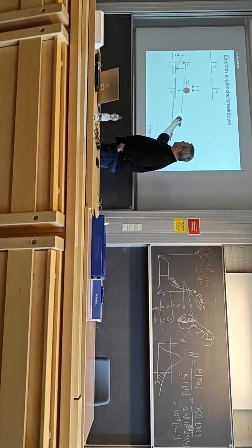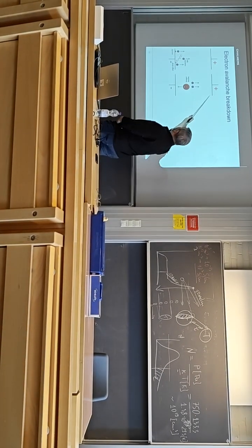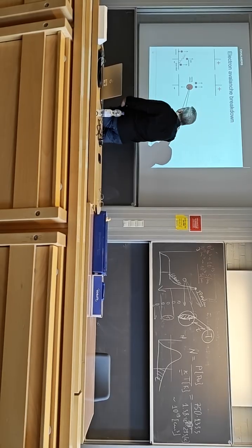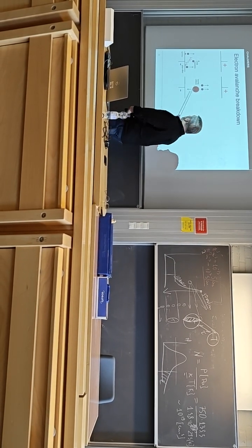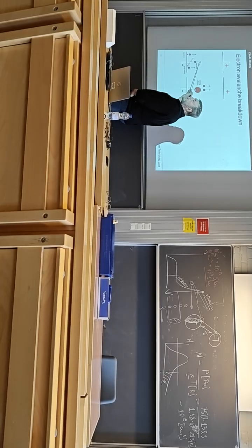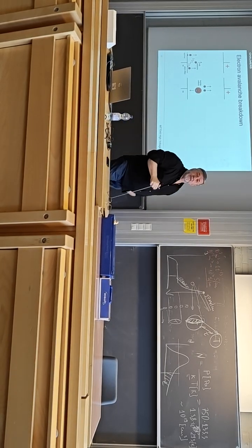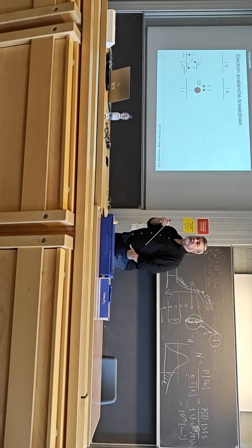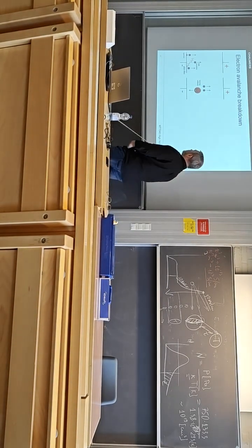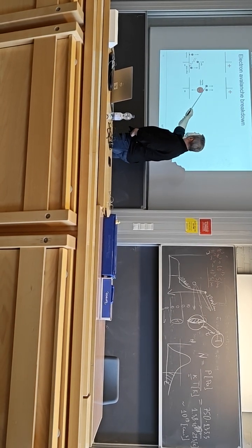All of these are put in motion because there is a field between plus and minus. The electrons move opposite to the field, towards the positive electrode, and the ions which are created move just opposite. Ions are created due to ionization collisions. So these electrons start moving, they gain the energy, q E lambda, which exceeds the ionization potential, and they create this one. Now we have 2 of them.